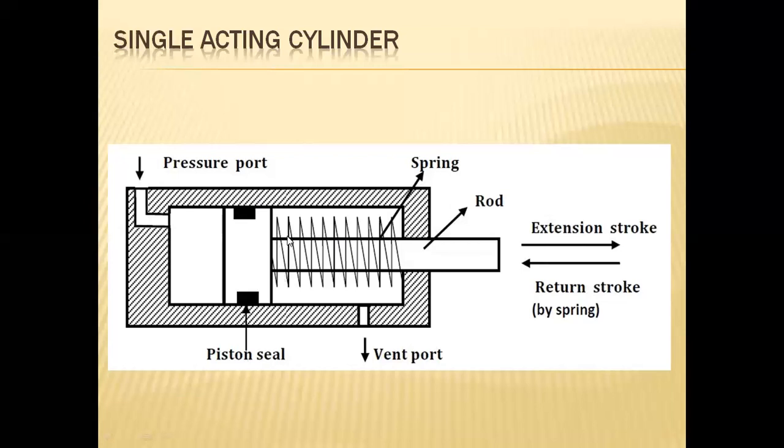And next, the spring will be compressed up to its capable range, and at that position a vent port is created, so that the vacuum already existing in this region will be led towards the atmosphere. If at all any fluid has been filled at this section, it will be drained to the oil reservoir.